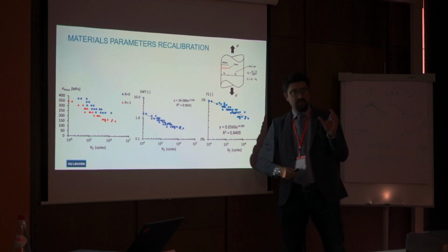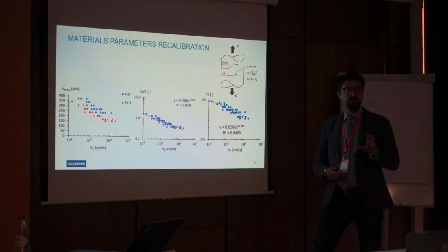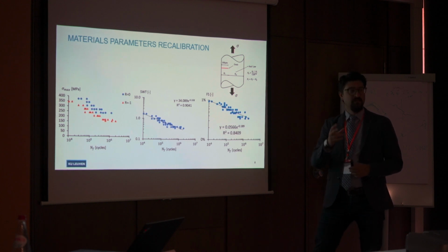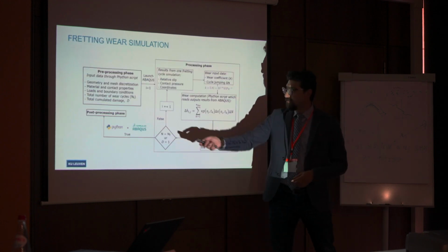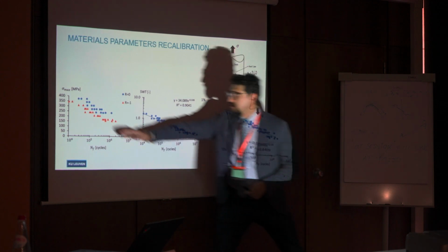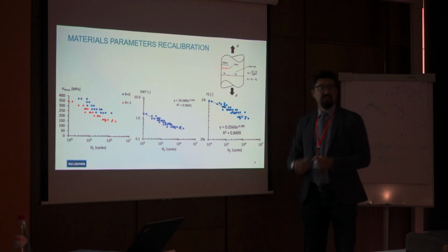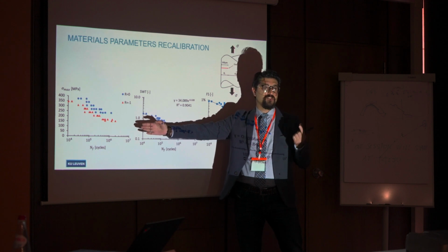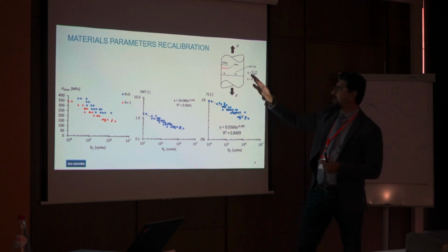But we wanted to be accurate when it comes to crack initiation lifetime. So for us, crack initiation was around 100 micrometer, which is actually the same size as one grain in that material. So what we did, we had, let's say, S-N curve data for the material in the dogbone shape, which is typically the lifetime of initiating a 1 millimeter crack. So we tried to fix this by a fracture mechanics approach.